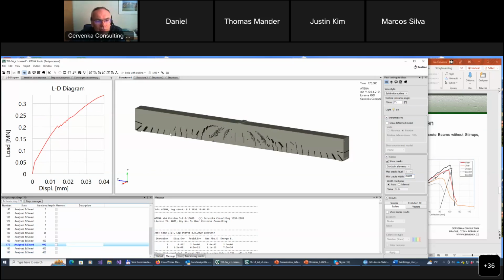We nicely see these bending cracks originally, then they changed to shear cracks. The shear cracks really did not fully develop. There are several of them because they are nicely addressed by the reinforcement stirrups, which took over.